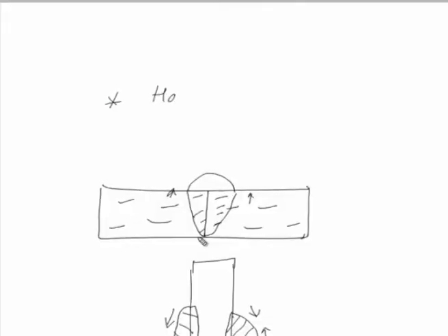Apart from the limited Z direction ductility and the tensile residual stresses, it is also facilitated by the hardened structure which is formed in the form of martensite and the presence of hydrogen in the heat affected zone.